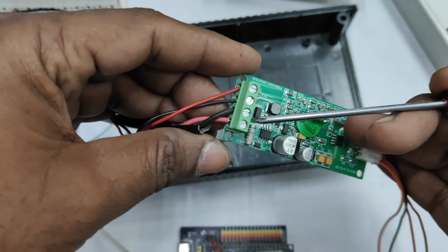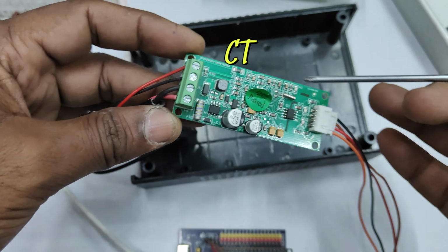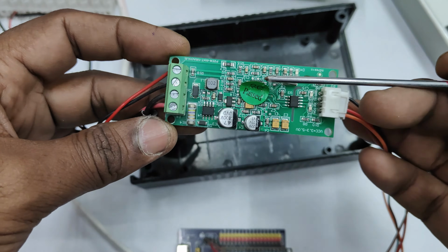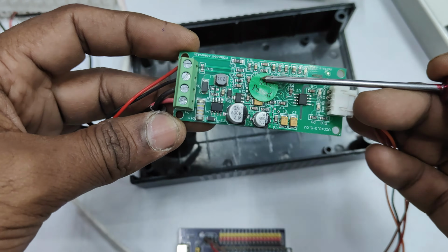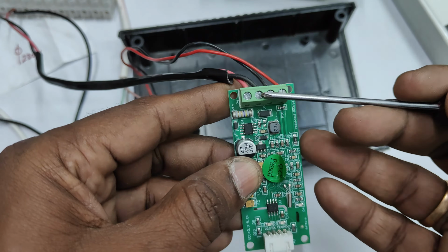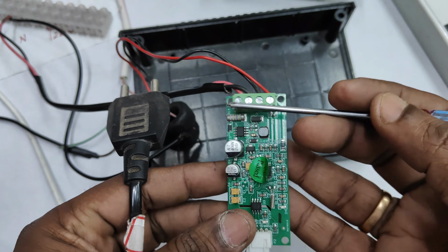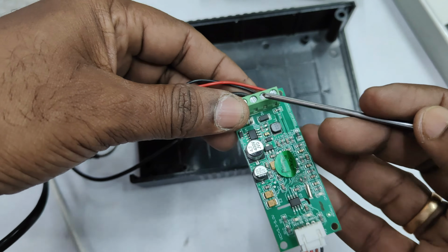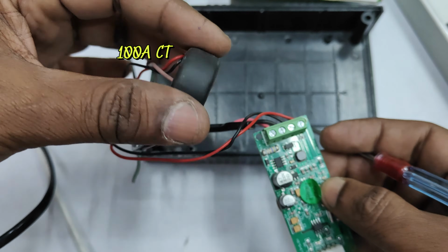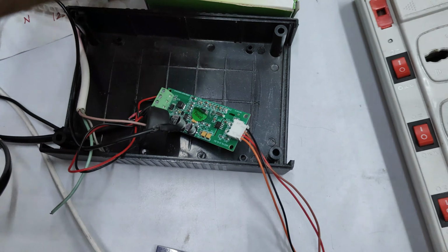It has got 4 terminals: the top 2 left terminals are for AC, the 2 right terminals are for the current transformer, and the bottom side is for TTL. This is capable of 3.3 volt operation, so you can easily connect it with ESP32. The top 2 pins are connected to AC directly, and the right hand side 2 pins are connected to the CT coil, which is capable of 100 ampere. Through this CT coil you have to pass the phase wire of the load.